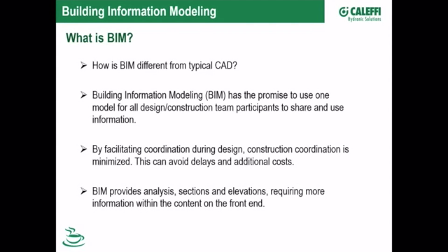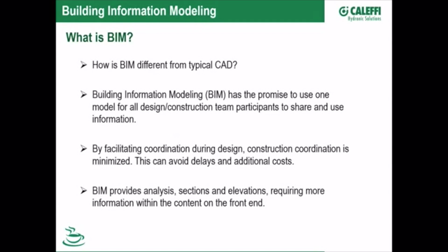A BIM project can also be shared amongst several users simultaneously, where a CAD file cannot. With CAD files, you need to open and close individual drawings as you work on them. With Revit, all of the views, schedules, legends, sheets, all that stuff is accessible from within the project browser. BIM models can also be linked together, allowing the different disciplines to access the building data. This linking also allows for coordinating between disciplines, minimizing collisions between system components. With BIM models being more robust informationally, they also require that greater care be taken with the content used within the project.